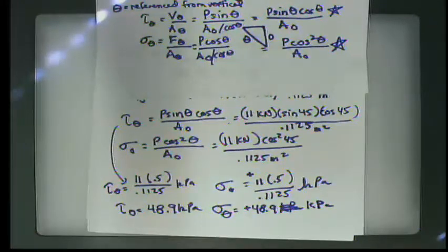Because cosine's maximum value is 1, therefore there you go. D and A are the same. Here, sine cosine is a little bit different, but to find the maximum tau, you could actually just take the first derivative of that expression and see where it is equal to 0, because you look for that 0, the maximum or minimum. But like I said, just ignore what I said about the 45 degrees. It's still true, but we don't need to talk about that yet.